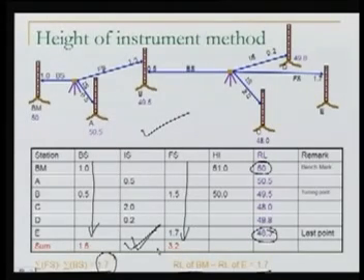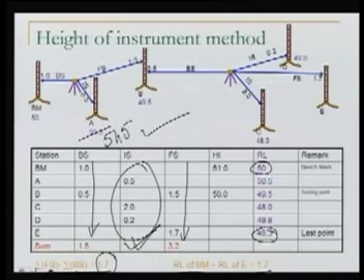Now one thing you will observe in this check is that we are only including foresight and backsight. We didn't include the intermediate sight. If by mistake some intermediate sight was wrongly computed, for instance, instead of 50.5 I write 51.5, we don't have a check for this in this check. Anyway, we'll see how we can apply that check later on. So this is the height of instrument method to take the observations in the field, do the computation and finally record it.